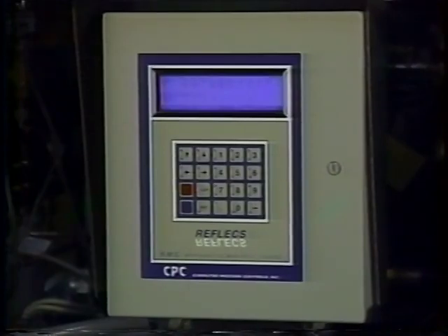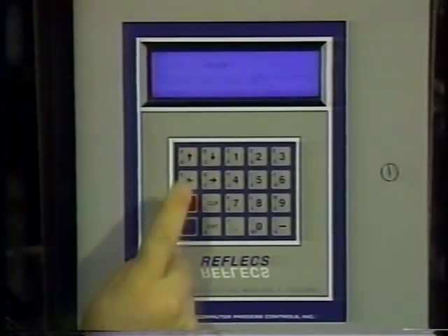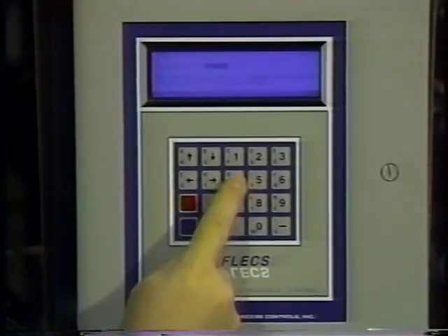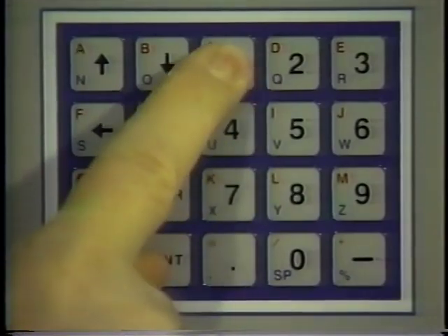The TRC comes with operational parameters programmed in memory. To view or change set points, log into the controller and go to the main menu. Press 1, which is pressure control. Then press 6, which is the pressure set points.